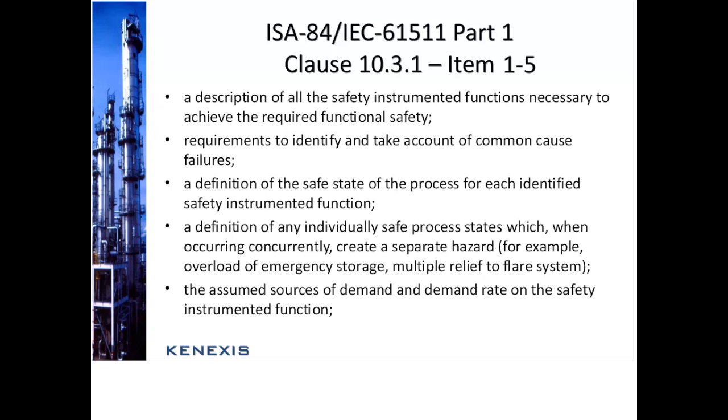A definition of any individually safe process states which, when occurring concurrently, create a separate hazard. This is common in a power outage, where all your processes go to a safe state. Your fail closed valves fail closed, and what happens then is you put an excessive load on the flaring system.